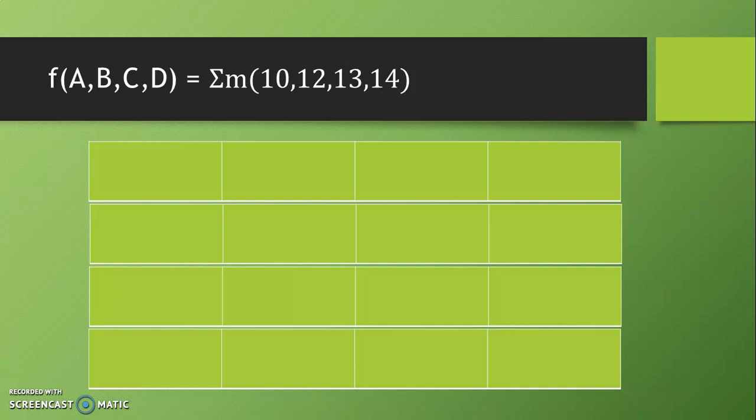So now, as usual, we have prepared the K-map with 16 cells. We have AB and CD variables vertically as well as horizontally. Then we write numbers. The numbers are very important: 0 0, 0 1, 1 1 and 1 0. So 1 1 and then 1 0 we take at this stage, that we should always remember. Then for the CD variables also we have 0 0, 0 1, 1 1 and 1 0.